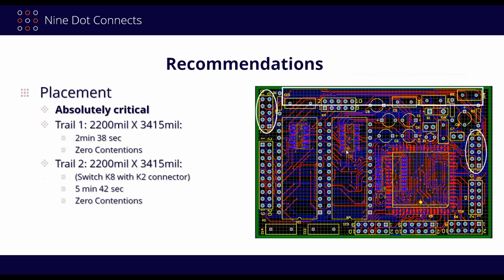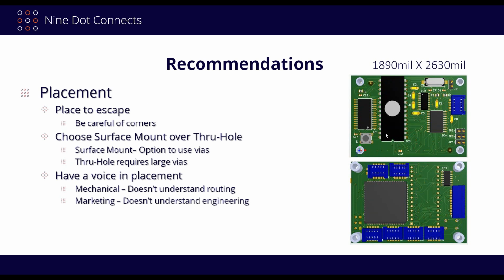So the original designs did have a lot of through hole here, and over time, actually through these experiments, we reduced them down to their surface mount equivalents where we could. So we didn't want to fake anything here. Anything that we could find and replace, we did put a surface mount on it. This is an EEPROM, which we couldn't find a replacement for, so that's why we left it in there.